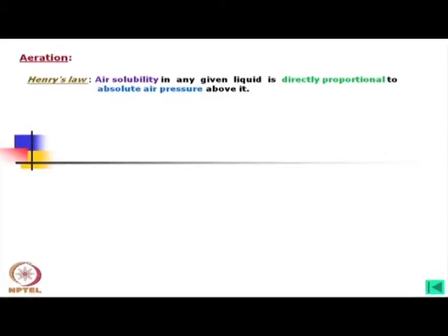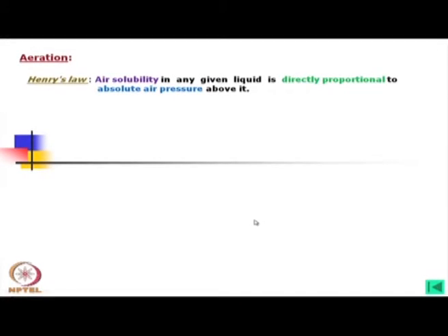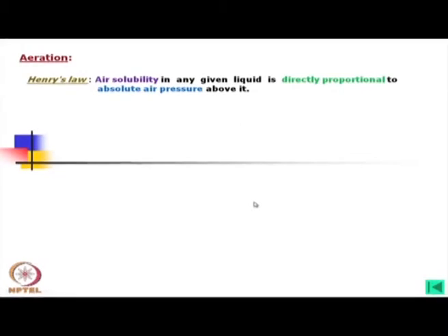That means, if you trap the oil in a vessel and pressurize it, the solubility will decrease. But for a particular oil, when it is exposed to atmospheric pressure, it has its own aeration inside it. That can be controlled by additives, but perhaps cannot be fully eliminated. Now, it can be found by experiments.